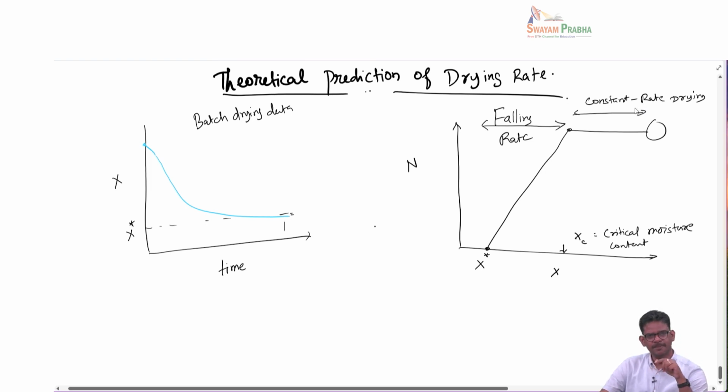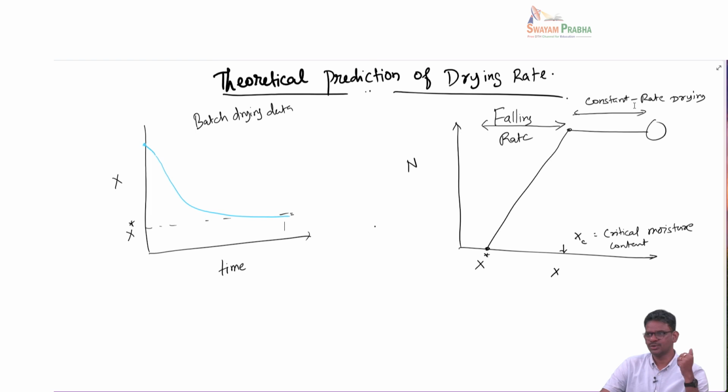So in that case, the drying rate is more limited by the gas that is passing over. What is its temperature, how much humidity it can hold, and what is the mass transfer coefficient in the gas phase. Those are the limiting conditions for constant drying.